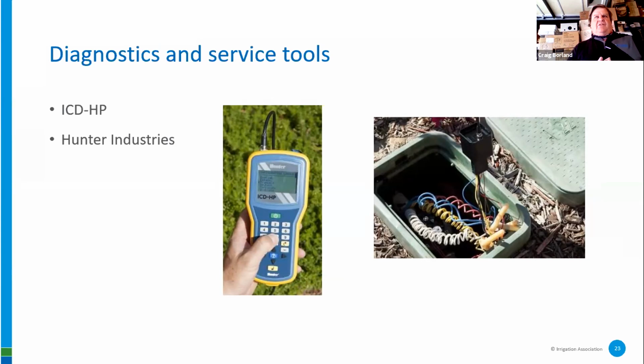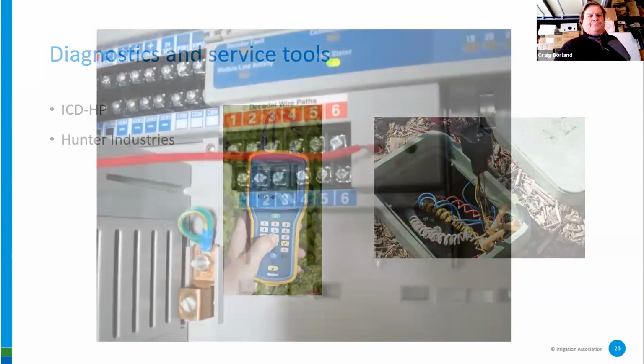You've got 50, 75 stations out there with 50 to 75 decoders. They're all Hunter decoders. Guess what? They only work with a Hunter controller. If you want to change a controller, you'll have to change all the decoders to match the brand the clock is. So that makes it somewhat guaranteed that what goes in as Hunter remains Hunter, what goes in as Rainbird remains Rainbird, what goes in as Toro remains Toro, what goes in as K-Rain remains K-Rain. They're brand specific. What valve is used, what sprinkler heads are used can be anybody's, but the decoder must line up with the clock.